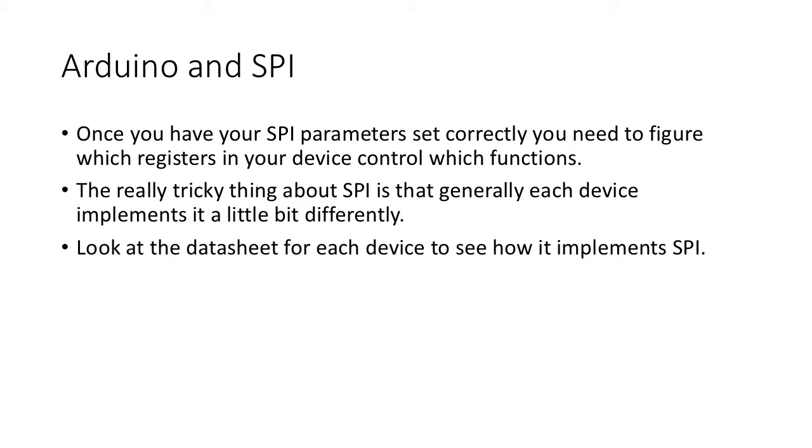You can typically reassign the pins that are used for the master out and the slave in, as well as the serial clock and the chip enable and the chip select. And as a result of that flexibility, you'll find that different microcontrollers, especially those which are integrated with various devices, behave differently.